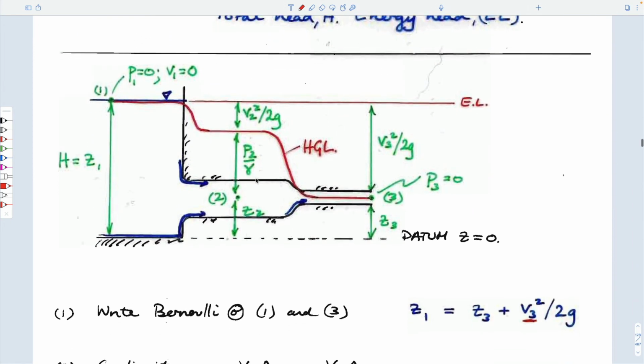And so if we take a simple flow system with a large tank with a pipe in it that contracts and then goes out at atmospheric pressure, we can chart all the components of Bernoulli as we go through from upstream to downstream. And when we're upstream, there's no velocity. The pressure, if we look at the streamline on the top, and we're going to take this streamline as we go through here.